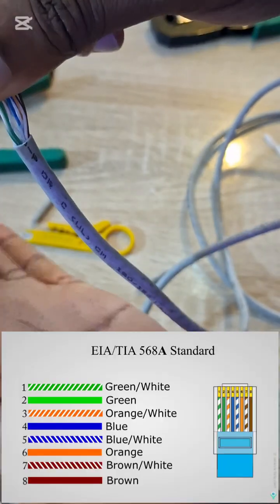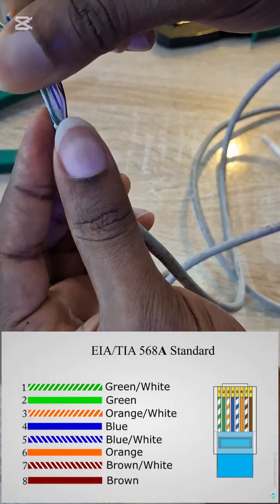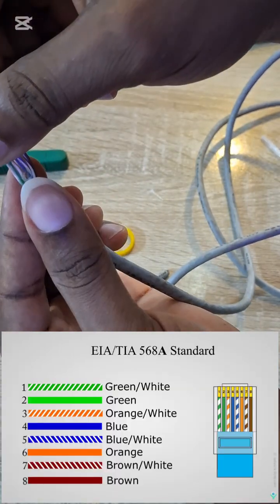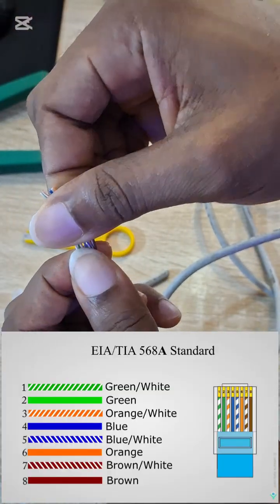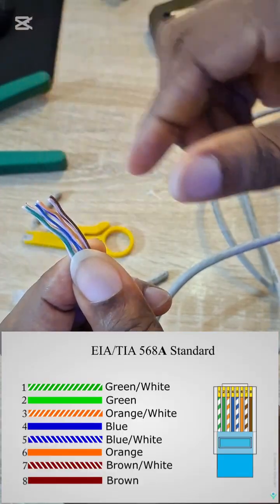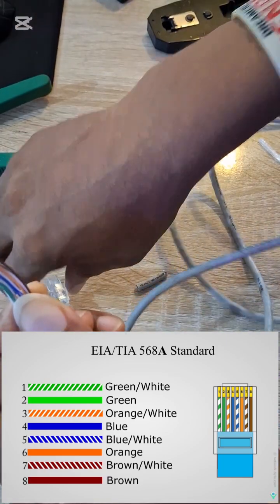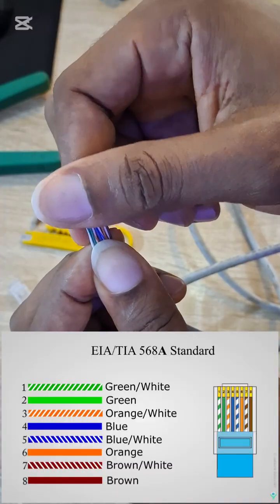Once you arrange it this way, hold it with your left hand. Try to get the smallest portion you can. Make sure they are well arranged. If they are not, when you fix them inside your RJ45, they will rearrange themselves, which will not give you the code.